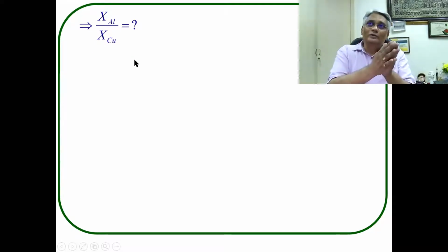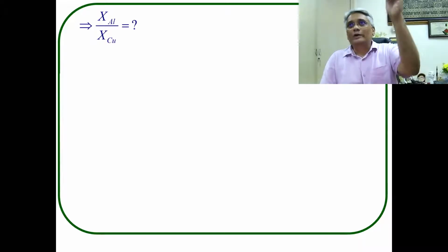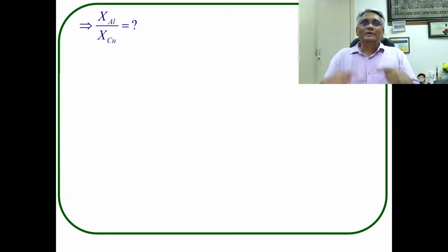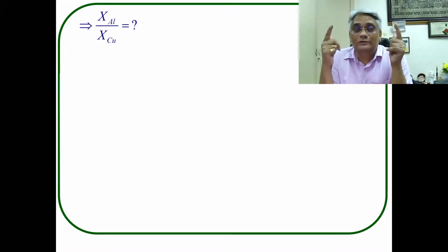So what we are trying to do is to get 2 weight% of copper and 98 weight% of aluminum. Is it okay to start with the same weight% ratio or not? This is always very important in thermal evaporation. In fact, many people make the mistake of taking the same weight% composition that you need to finally get on the thin film.